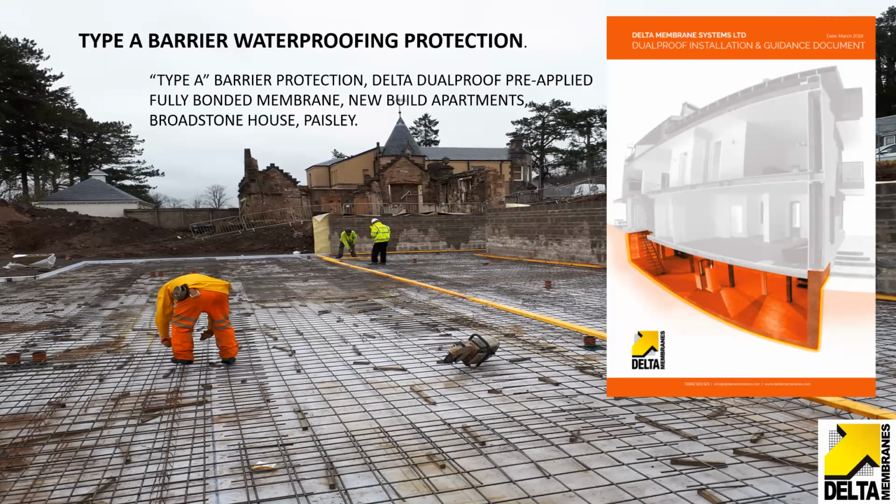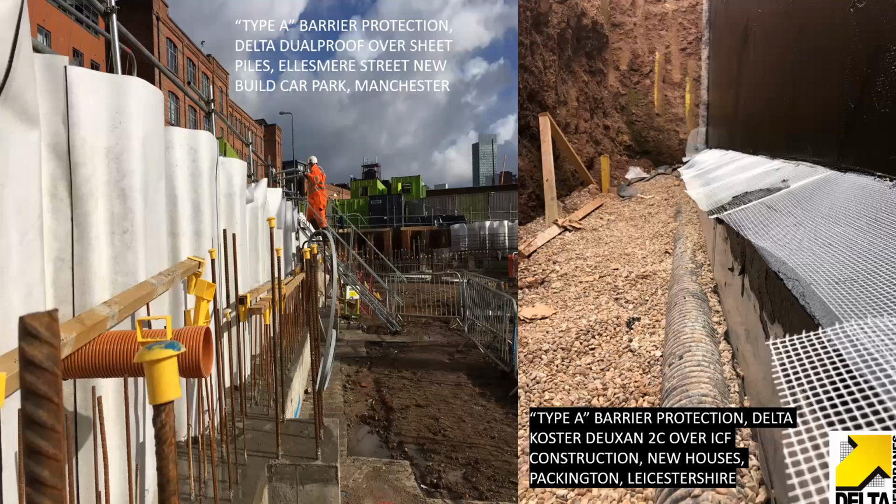So here we have an apartment block in Paisley, which is basically not far from Glasgow. We have a pre-applied fully bonded membrane here. And if we could zero in on that membrane, we'd see it's got a fleece on the top of it, which is going to fully bond to the concrete. So if there is a defect, then the defect will stay isolated to the point at which the defect occurred, instead of tracking between the structure and the membrane and finding a construction joint or something to come through. And that's an example of a pre-applied fully bonded type A membrane. It's the same membrane on the external face of some sheet steel piles.